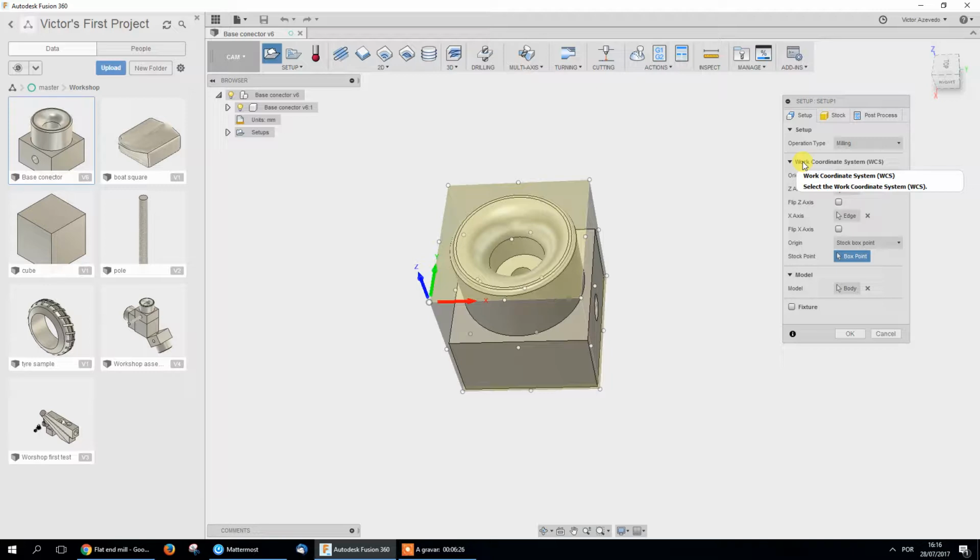So, in one of the machines, the 0 is made with the tool, and the other has a tool probe, or the work probe. For me, after placing, let's say, the block of material, if I place, let's say my hand is the vice that grips the material, if this is the block, it's harder for me to remove a point down here than up here.